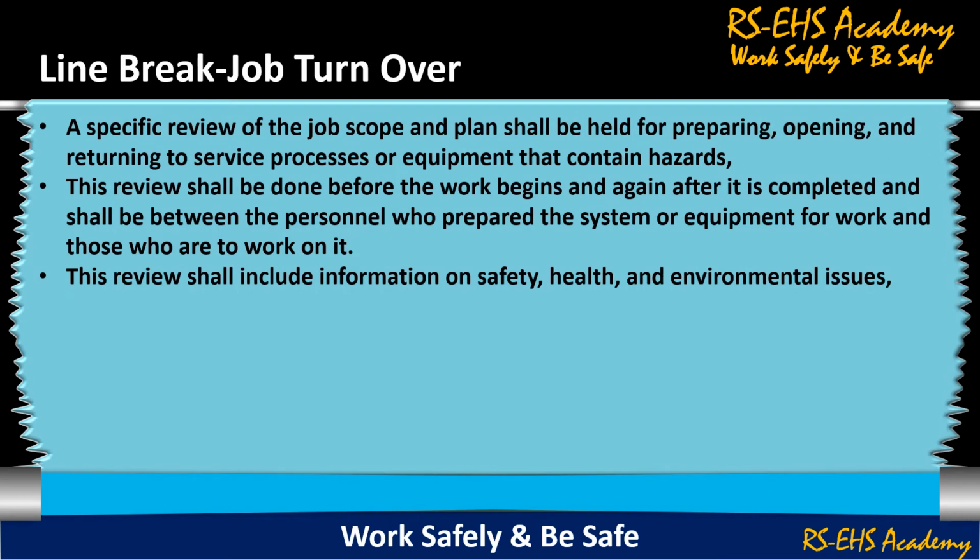Line break, job turnover. A specific review of the job scope and plan shall be held for preparing, opening and returning to service processes or equipment that contains hazards. This review shall be done before the work begins and again after it is completed, and shall be between the personnel who prepared the system or equipment for work and those who are to work on it. This review shall include information on safety, health and environment issues.